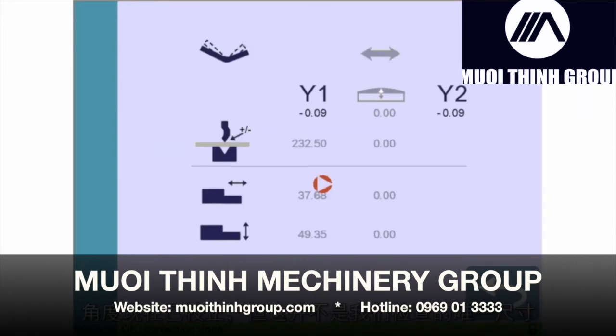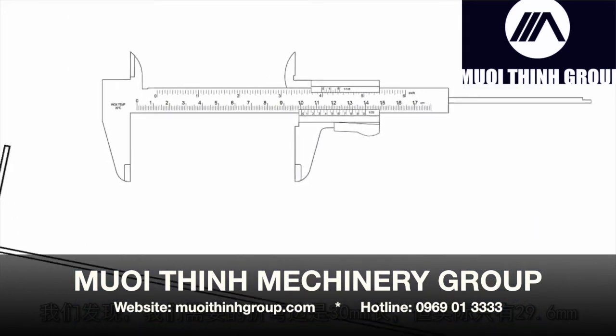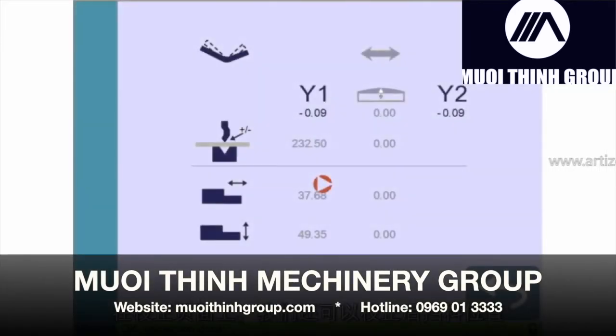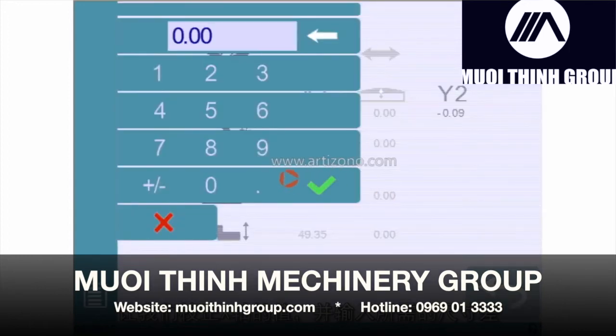Our angle is now corrected, but it is not the only dimension we must check. We wanted the flange to be 30mm long, but it is only 29.6. On the correction page, we can also correct the back gauge positions. Let's correct the x-axis value here and enter the difference to the desired dimension.